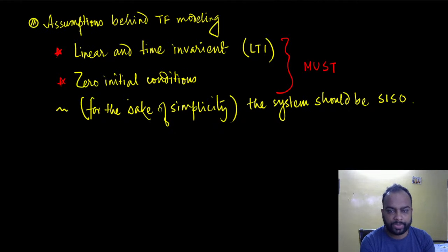If something like that happens, then I do not have any reliable way of using transfer functions to figure the response out, right? So I have a system where there are non-zero initial conditions, and I have a transfer function of the system. Then I do not really have a way of figuring out the response of the system to those non-zero initial conditions, because while developing the transfer function model, we completely discarded any initial conditions really. So if there are any initial conditions, we cannot reliably figure the responses out. So that is something you have to remember.